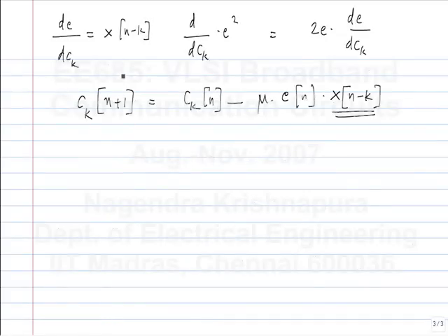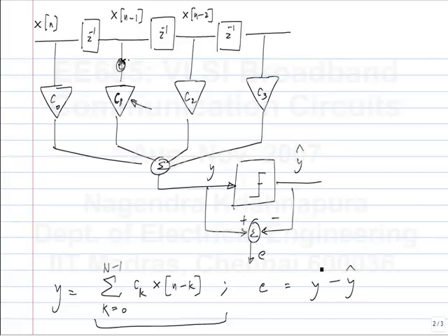So I do this for every coefficient. That's all. Every coefficient is updated based on the error and whatever each coefficient is multiplying. The error is the error in the received value with respect to the target. Error in the output value Y with respect to the target. So every coefficient is moved so that the error in this is minimized. Okay.